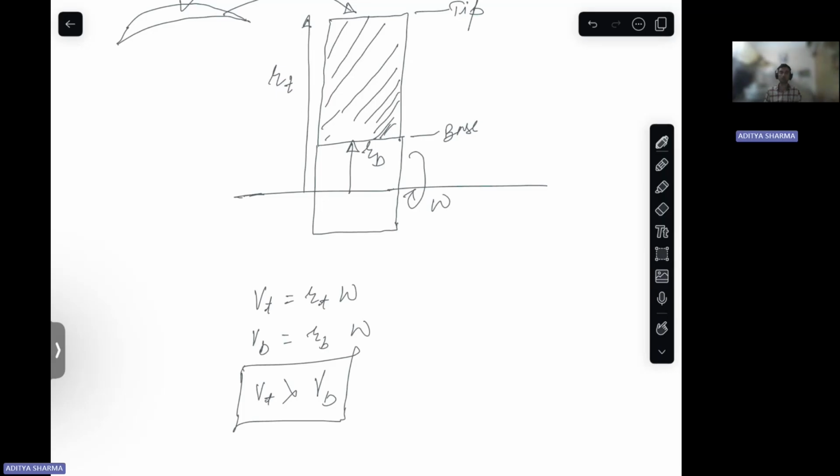So when we draw our velocity diagrams for our blades, we take a single blade velocity, but in reality the situation is different. But anyways, to represent our blade, what we do is we take one mean velocity of these velocities from base to tip.